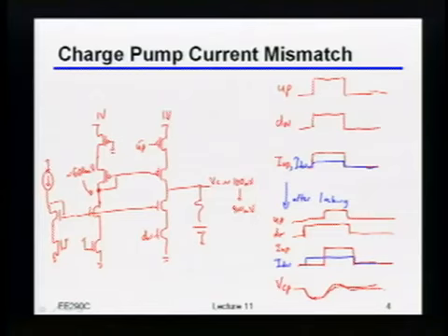You had a question? Yeah. So doesn't the loop filter that out? Well, no, because remember, this glitch is happening every reference clock. And then this glitch gets fed to my VCO. And all the VCO does is say, okay, my instantaneous frequency just tracks whatever this control voltage is. So yes, you can argue that that's an integration.